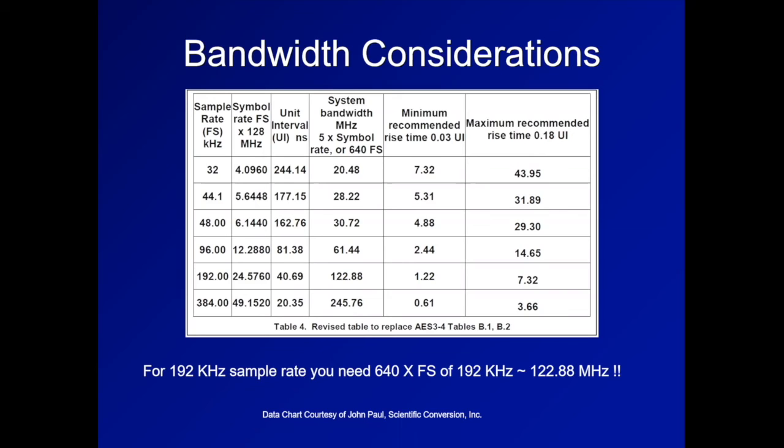Because if you look at what you're doing, this is a system of square waves. Okay, and square waves need a lot of bandwidth. Why? Because they're harmonic rich. And you need two things. You need bandwidth and you need phase linearity within the passband. And so these are two very, very important aspects of what you need to have. So we've had a big jump up. It's almost about a fourfold, almost fivefold increase in bandwidth requirement for 192 kilohertz to do it properly. Okay, next slide, please.